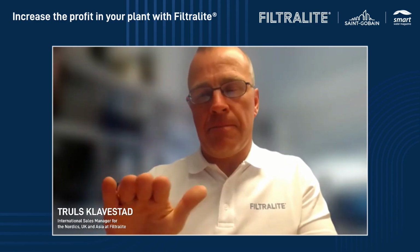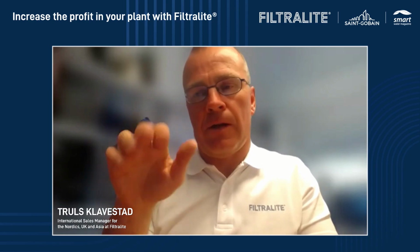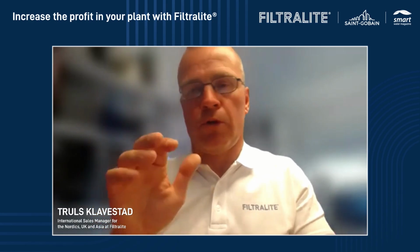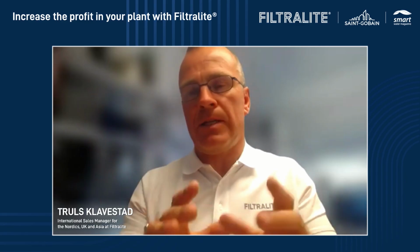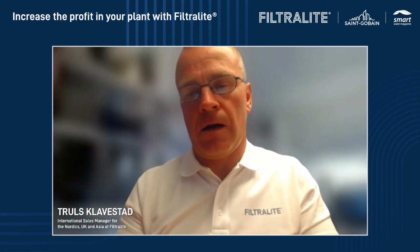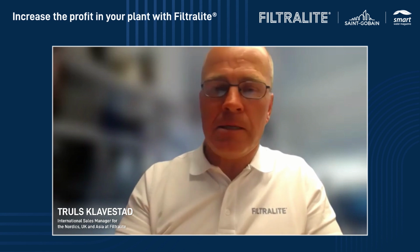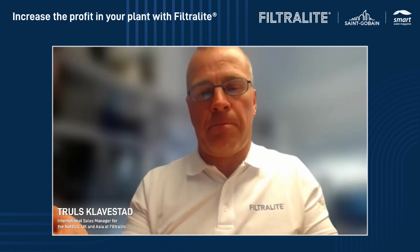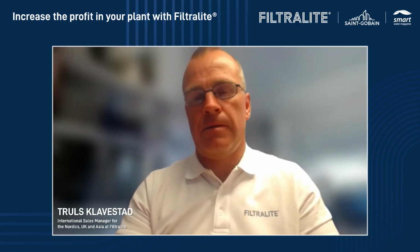But if you keep the same grain size and increase the filtration speed, that will also have an influence on the water quality. So all of these things need to be taken into account in all the different decisions. But yes, I agree with you. When you make a comparison, you have to compare apples with apples. If not, it doesn't make sense.